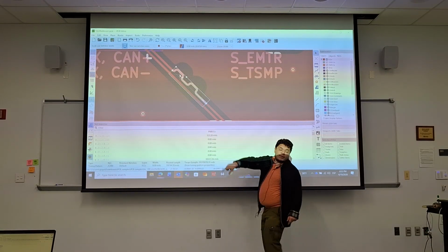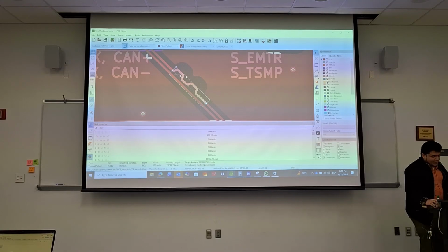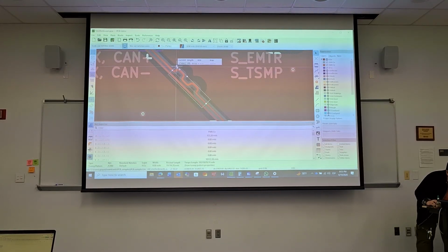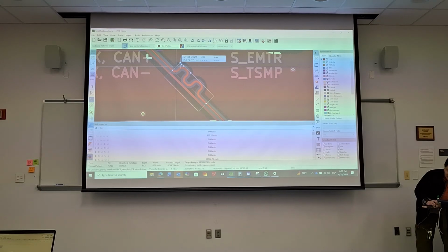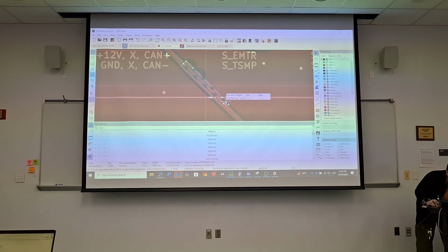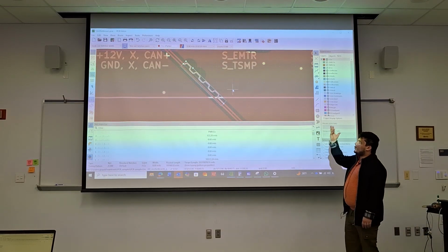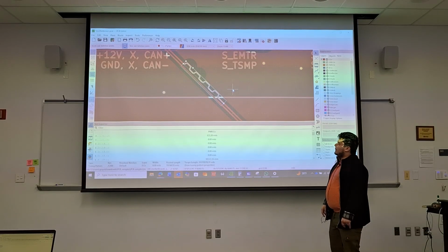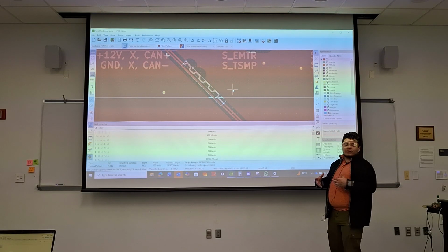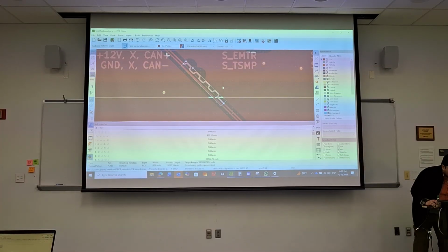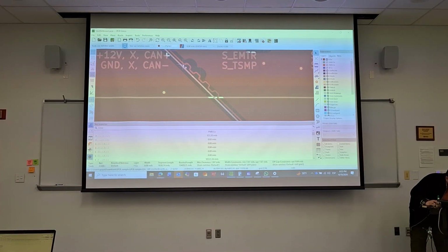And so you have to, thankfully this is manual, you have to adjust it here, right? So where it was, that's way too big. You're decoupling. Really, this should be closer to here. And when you lose that height, then you kind of compensate by adding more, right? So that's how you would do that. And like I said, you want to do that so that they're close to or within 100 mils.